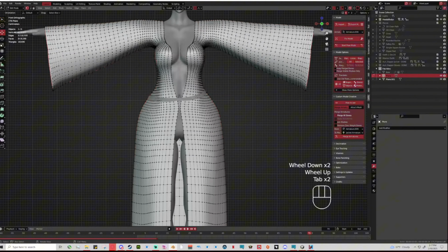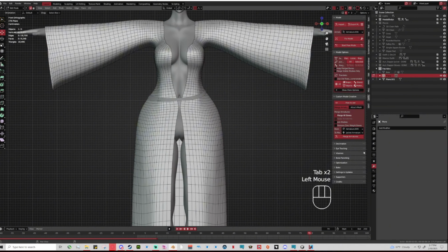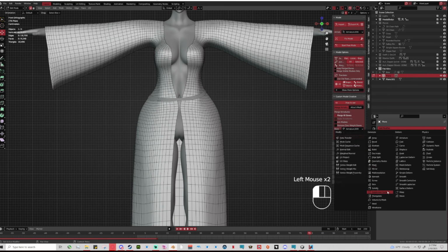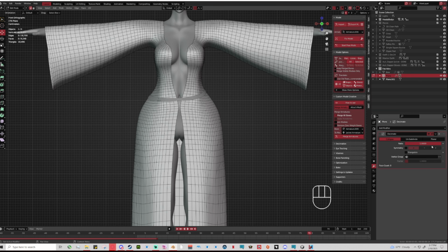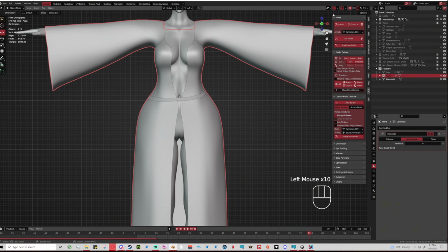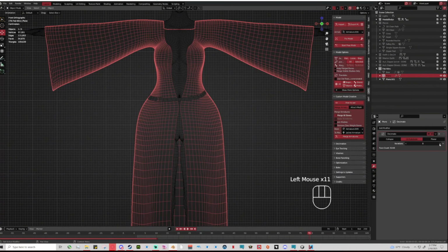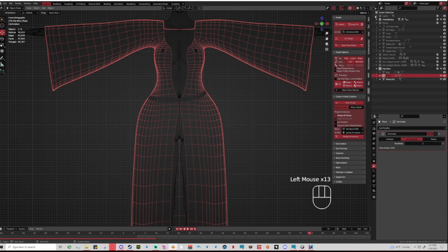So there's a few different ways that you could go about cleaning up the wireframe of your asset. You could use a modifier called decimate. Where is it? There it is. Decimate, unsubdivide, and you can up it. It's not going to show you right now because we are still on our material preview and we are in edit mode. So if you go to object mode and go to wireframe, you can actually watch it change there.